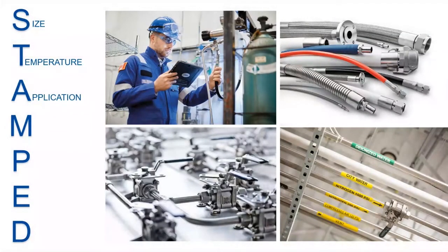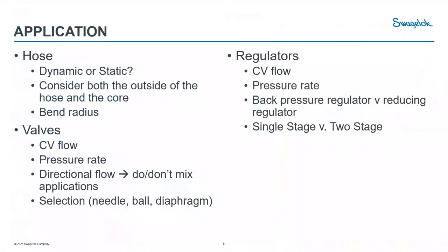Next, we'll talk about applications as they pertain to the S.T.A.M.P.E.D method. Something to consider in terms of your hose application is if your system is static or dynamic. A static application is a system that contains no movement as part of its function, so a regulator panel coming off of a tank. A dynamic application is something that has motion to it, for example, a tire press machine. If you do have a dynamic system, you want to stay away from metal cores because those can crack and cause leaks. Because of this, you always want to think about both the sleeve and core of the hose when you're choosing the correct one for your application.